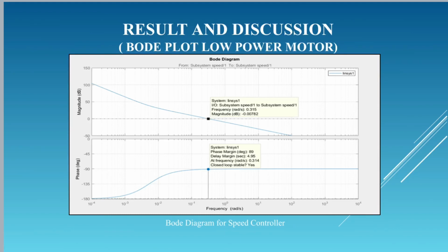We express that the performance of both speed and torque controller for the low power DC motor gives a fast response, minimum overshoot, and zero steady state error, since the values of bandwidth are large with the values for phase margin over 65 degrees.